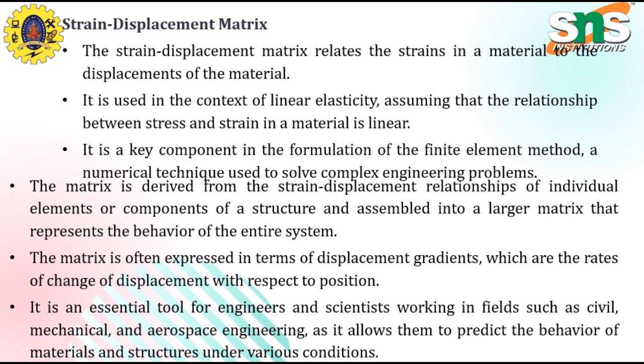The strain displacement matrix is typically derived from the strain displacement relation of the individual elements or components of a structure, and then assembled into a larger matrix that represents the behavior of the entire system. The matrix is often expressed in terms of displacement gradients, which are the rate of change of the displacement with respect to position.